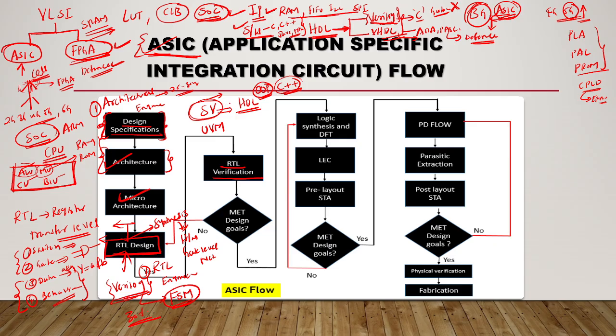And UVM is not a language; it's a methodology. Like in SV, there is no particular test bench. Suppose you want to write a test bench for I2C, you need to write it separately. Suppose you want to write one for UART, you need to write it separately. That is a robust test bench. So the companies decided they want a unique verification methodology and a unique test bench. That is how they came up with UVM, Universal Verification Methodology.